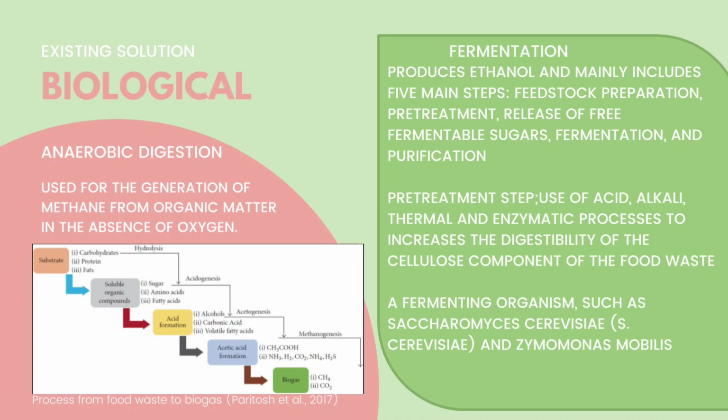The first step is hydrolysis, where substrates are converted into soluble molecules. Extracellular enzymes called hydrolases are used to conduct the hydrolysis reaction. Hydrolases can include esterase, glycosidase, and peptidase. This step transforms carbohydrate into sugar and converts lipid and protein to long-chain fatty acid and amino acid. In the second step, fermentative bacteria transform soluble molecules formed at the hydrolysis stage into volatile fatty acid, lactic acid, alcohol, and CO2. The main products in this step are acetic acid, propionic acid, and ethanol.